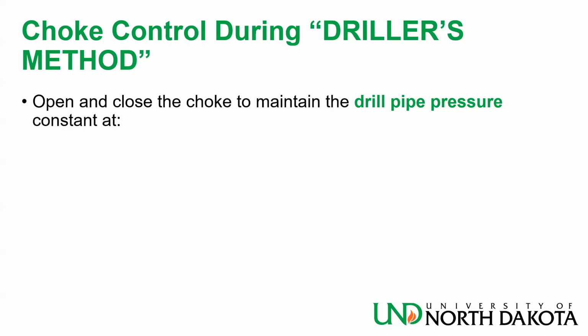The pressure transient of the mud, the choke will tell you kind of instantaneously what you're doing to it. Whereas if you waited for the drill pipe pressure, you'd have to wait 1 second for 1,000 feet. There is some lag time involved in the response. And it's a good point, Justin, you are making, because the app has an option to turn lag time on.